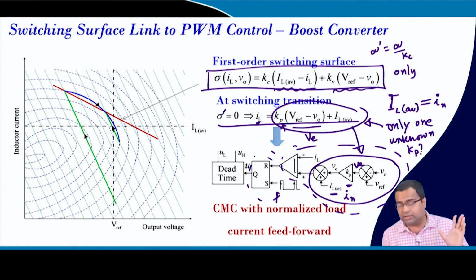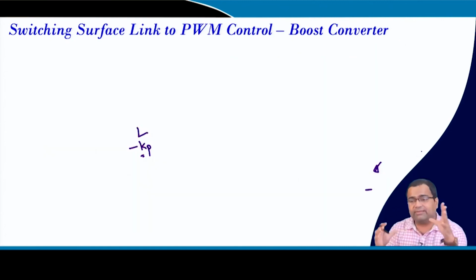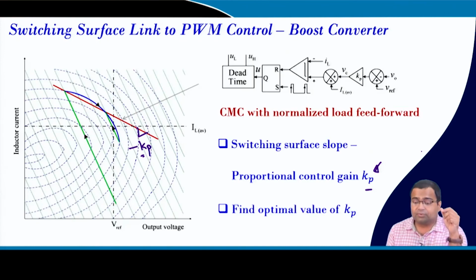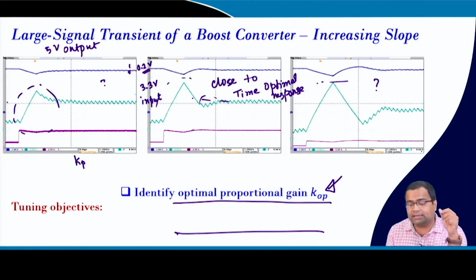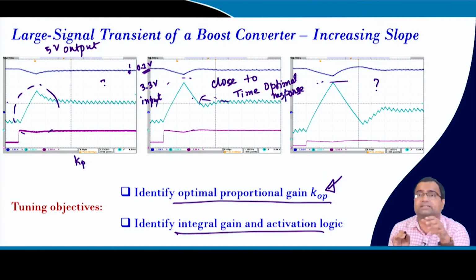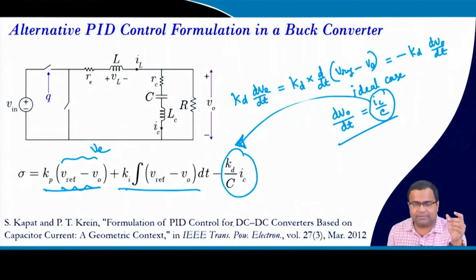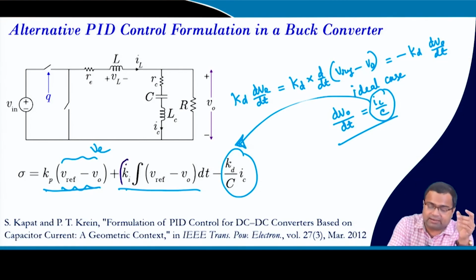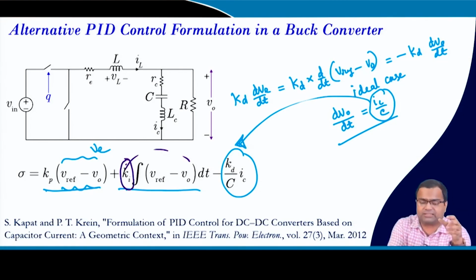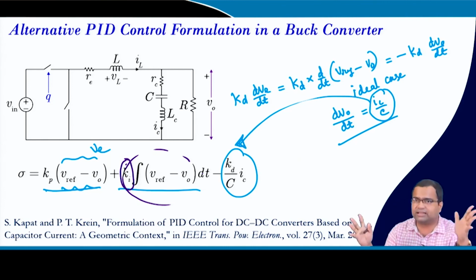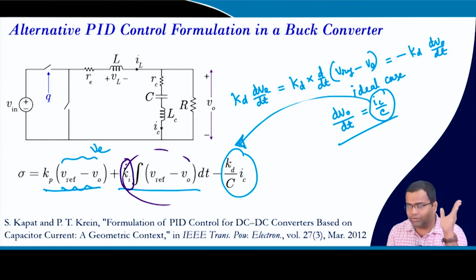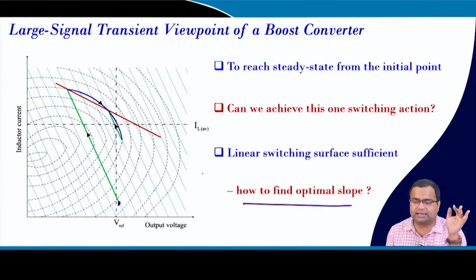So, we do not need to take the derivative gain, it is already taken care of, only one. The only thing is that we are incorporating an integral action like a PID controller, which we have discussed even before that. Since its action will be much slower, we will choose the integral gain based on the small signal derivation, that is fine, and we will only try to eliminate the steady state error. Okay.